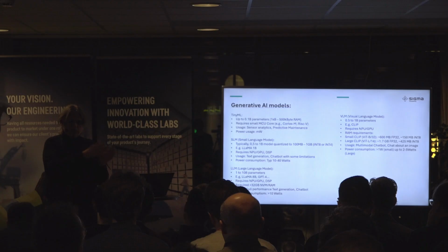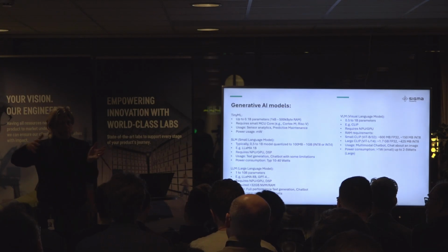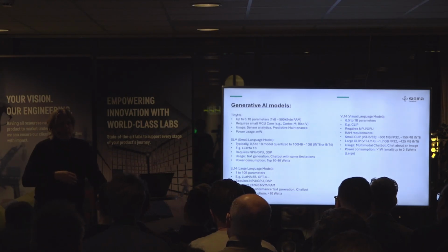Multiple video streams? Well, okay, so then it's more expensive. Do you want to do computer vision? For sure, a Linux system, not an MCU-based system. Do you want to have a vision language model where you can ask and discuss about the picture? Then the higher scale, the more expensive solutions. And you can have 30 frames per second or even 60 frames per second in real time, having inference response within the same frame. Like, to me, that's mind-blowing.